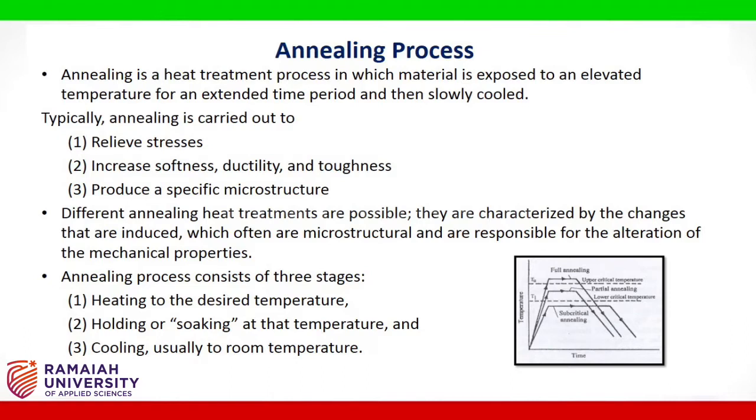They are characterized by the changes that are induced, which often are microstructural and are responsible for the alteration of the mechanical properties. Annealing process consists of three stages: heating to the desired temperature, holding or soaking at that temperature, and cooling, usually to room temperature. Normalizing.